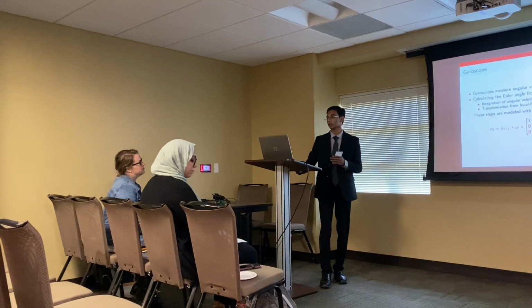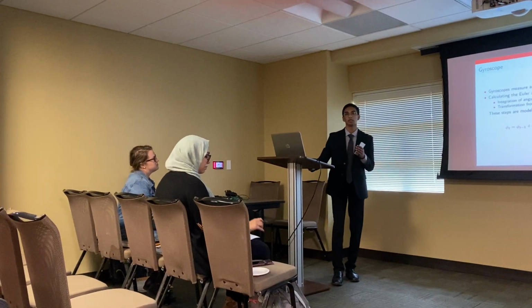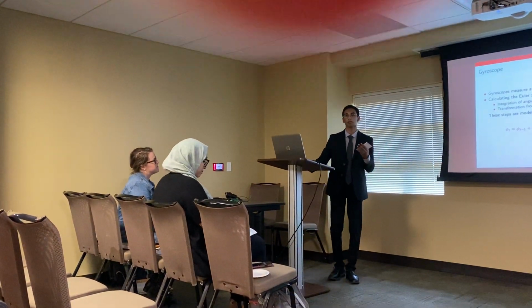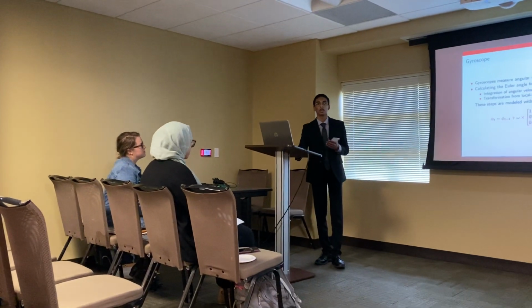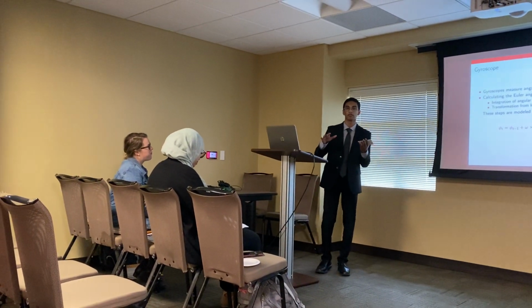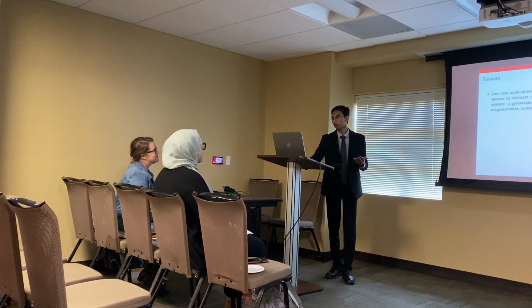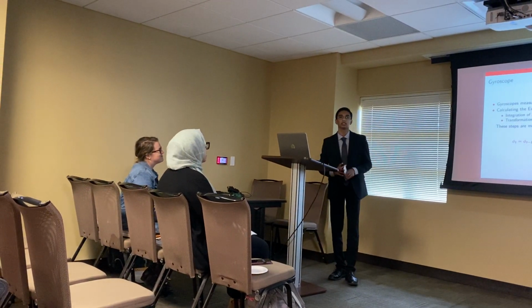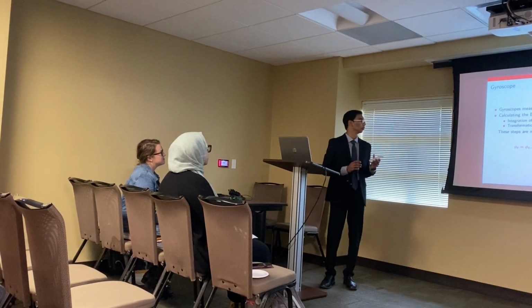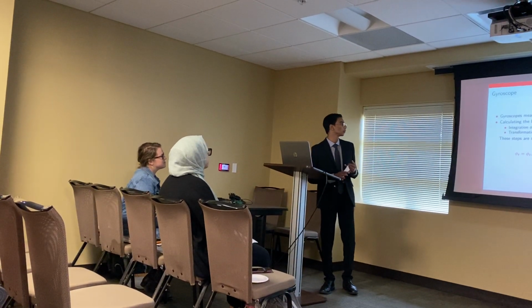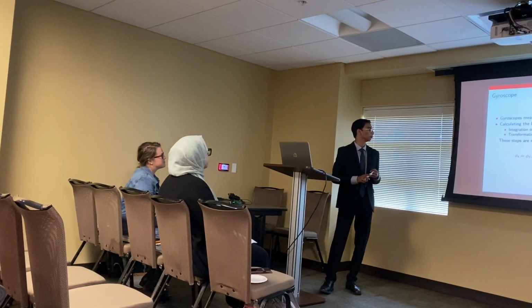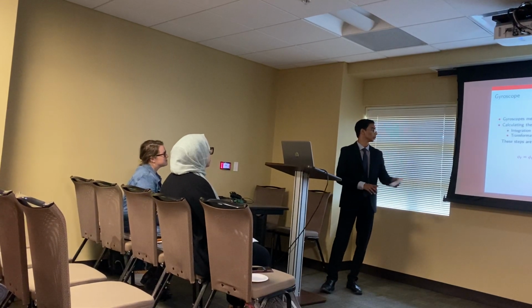These angular velocity measurements we get from the gyroscope are in what's called a body frame or a local frame, and this is the reference frame of the actual craft. These measurements need to be transformed into the global reference frame, and the integration and the global reference frame transformation can be modeled by this equation, equation 2, right here.